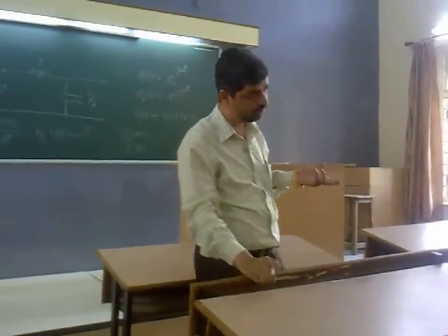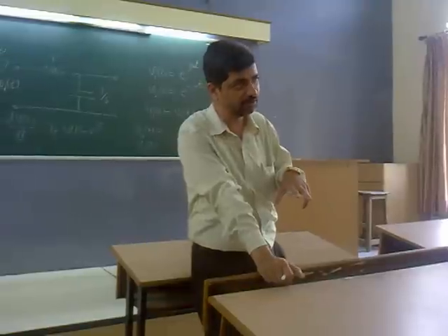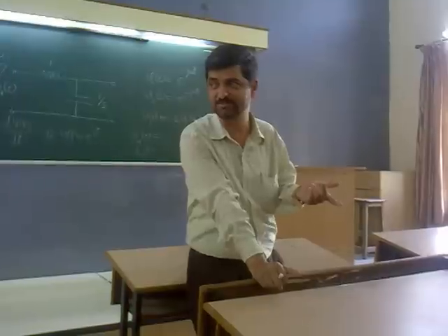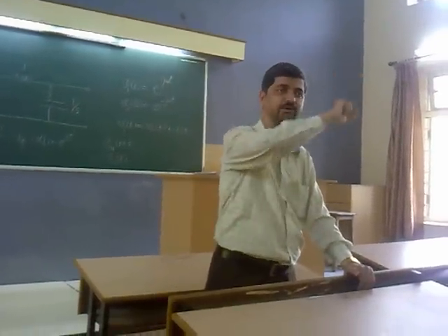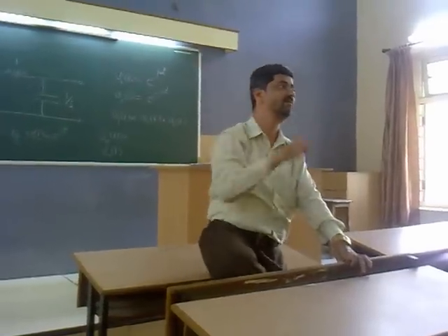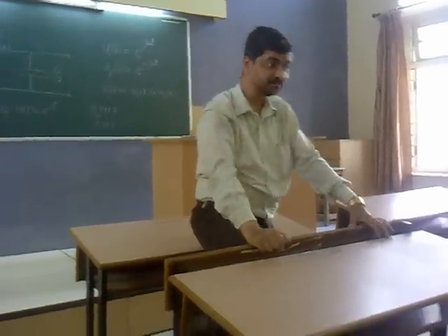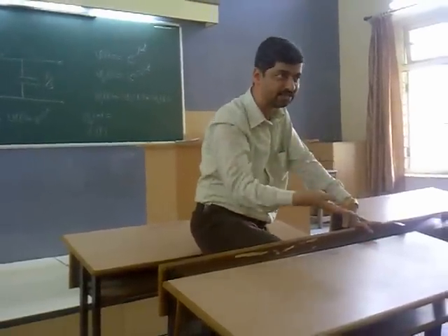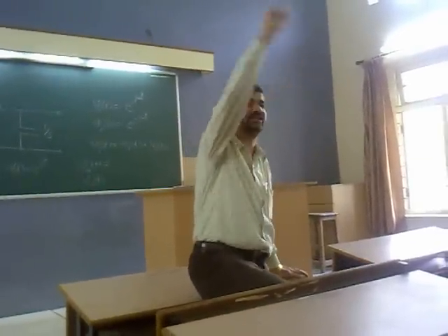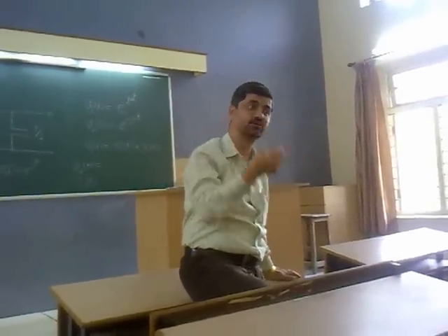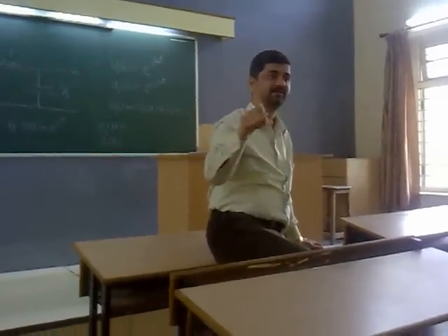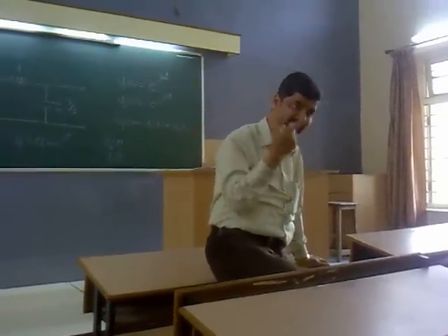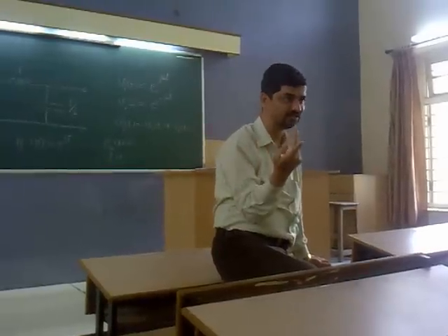I don't know whether you do have a self-talk. If you do, then these questions must have come to your mind: all right, that phasor is there, we accept. Rotating with plus omega like this, minus omega like this, that is also all right. If projection on the diameter is sinusoidal, that's also all right. But who takes the projection and how? Actually, there is no projection, but one phasor like this and other phasor like this, when they add together, their addition is always on the x-axis, because their imaginary components are equal and opposite and they cancel.